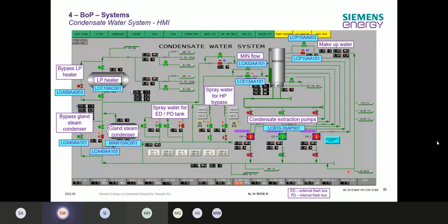We have here on the right side the demin water connection. So this is coming from demin water pumps, demin water tank, and therefore getting one time into the system connection over here so that you can fill up your demin water system after an outage, for example, or keeping it under pressure. That's the reason.